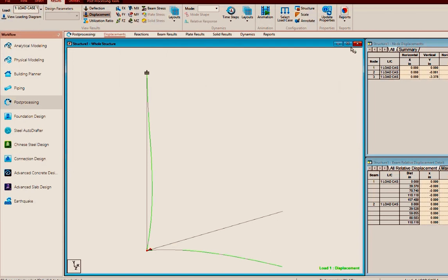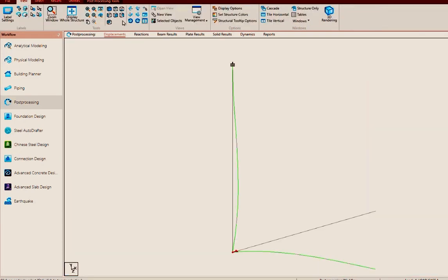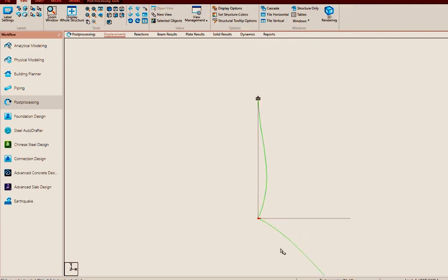If you see here this deflection shape, what we had explained earlier, our understanding is correct. You see here, this is the 90-degree it has to maintain. This is a single curvature, but this beam it has to maintain in this one, and here it's fixed, so it will be a curvature. This is one curvature, this is one curvature. There is a change in the curvature, right? It looks like this, it goes like this.